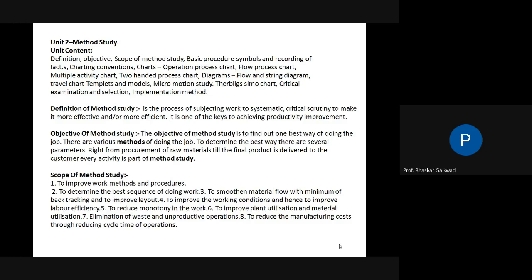Okay, in batch production, it should not be like that. In batch production, it actually depends upon the process. For example, a number of processes we are doing on the lathe machine, some processes we are doing on the milling machine, some on the shaping, planers, CNC, VMC, like this. We are grouping all of these. This is actually batch production.